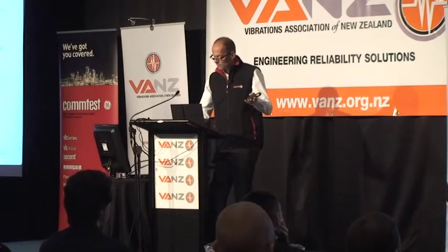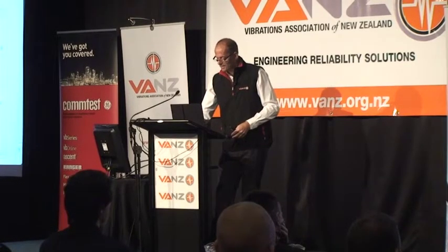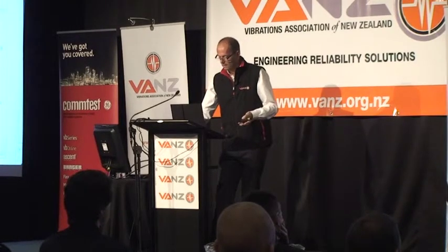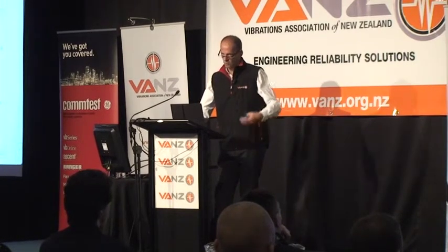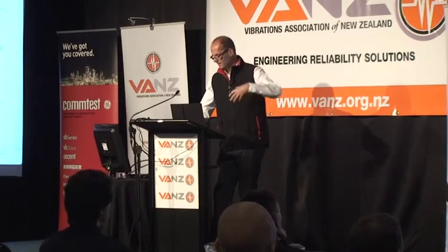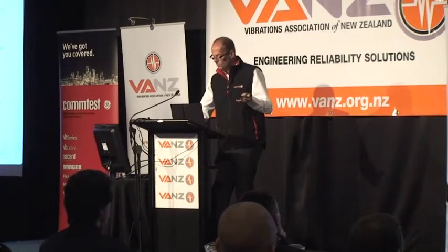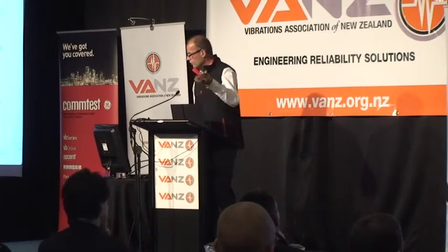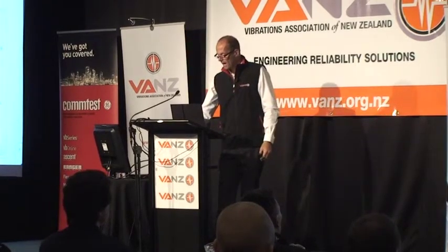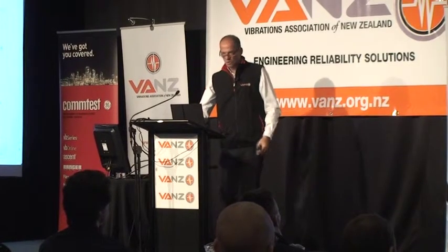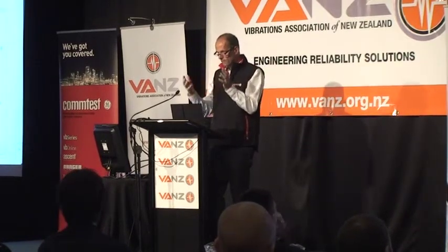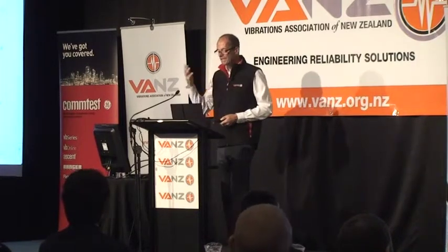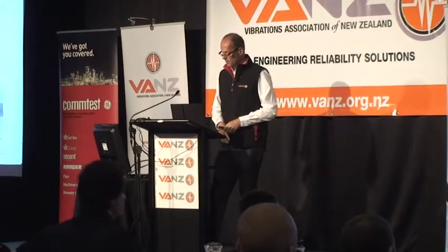And, we can switch to this mode. There's the vibration from the bearings, and as I say, there might not be any vibration. There might be a little bit of vibration. That's something we're going to watch for. If there was unbalance or a bent shaft or angular misalignment, there's a few reasons why. There's the vibration at the running speed, often called the 1x vibration. And there's our fan vibration. So the beauty of the spectrum is it's showing us all those little individual sine waves and everything else, making it easier to understand, to see what's going on with the machine.